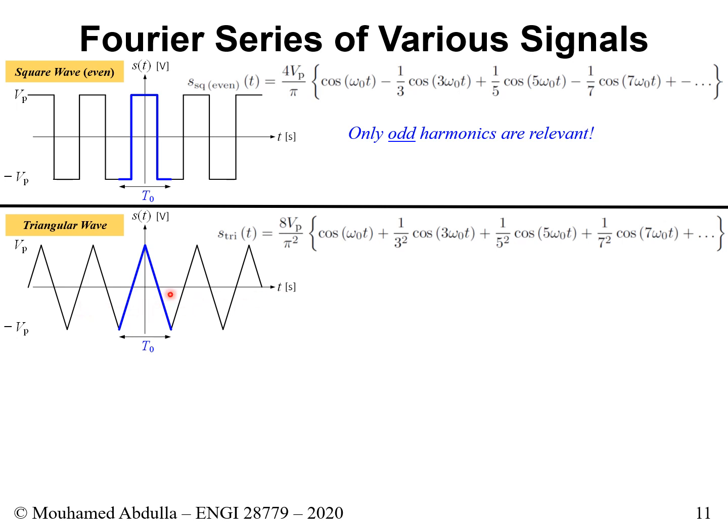Do we expect to see a DC offset? Well, if the signal is an even signal like this one here, you can project it on this axis. It is an even signal. A DC offset is possible, but you have to find the A naught, and A naught is essentially the average of the signal. So simply by looking at it, the average is here, it's 0.